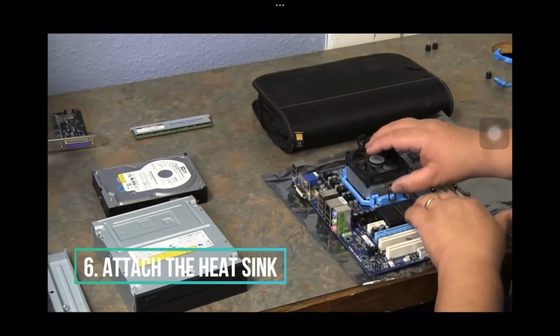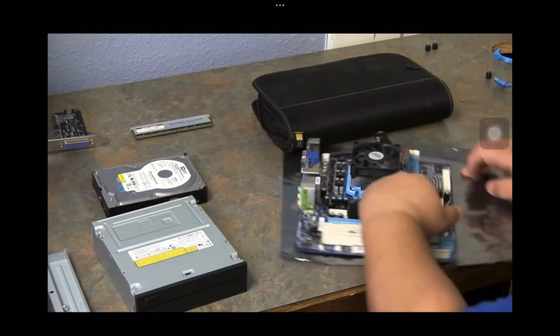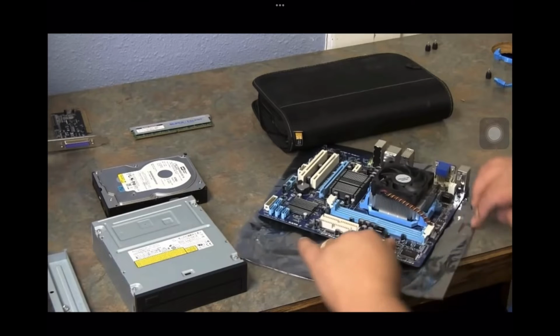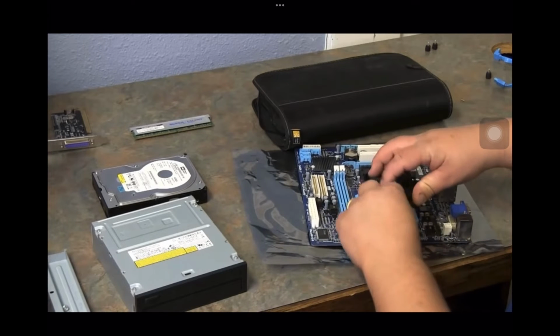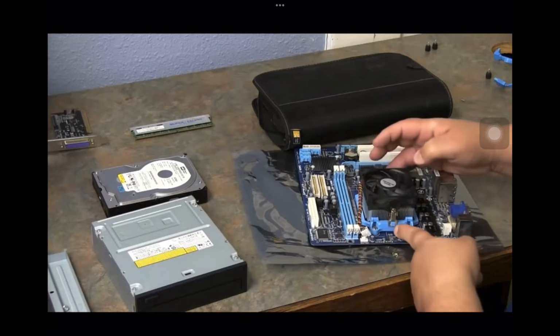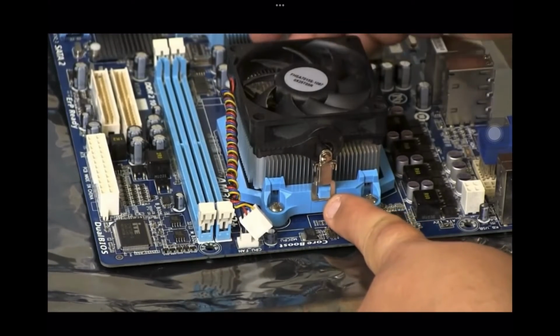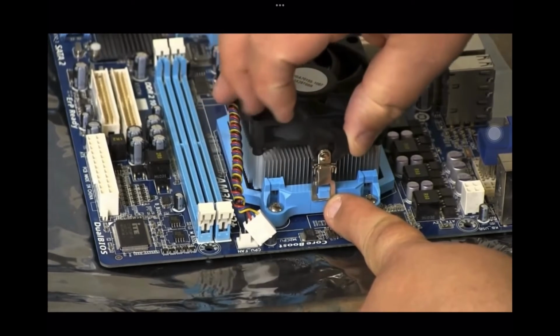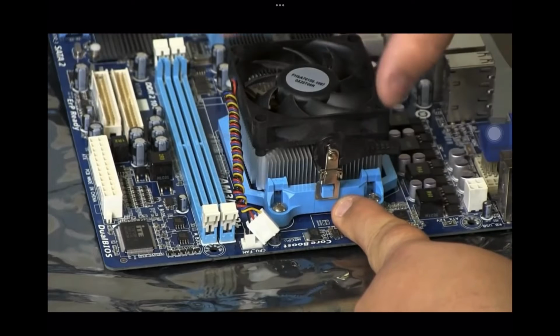Step 6 is attach the heatsink. This varies from heatsink to heatsink, so read the instruction for your processor. Most stock coolers attach directly over the processor and clip into the motherboard. Aftermarket heatsinks may have brackets that need to be attached underneath the motherboard. Skip this step if your processor has an installed heatsink.